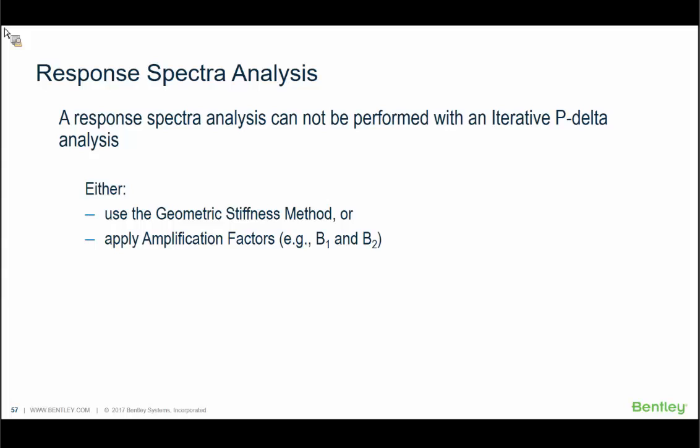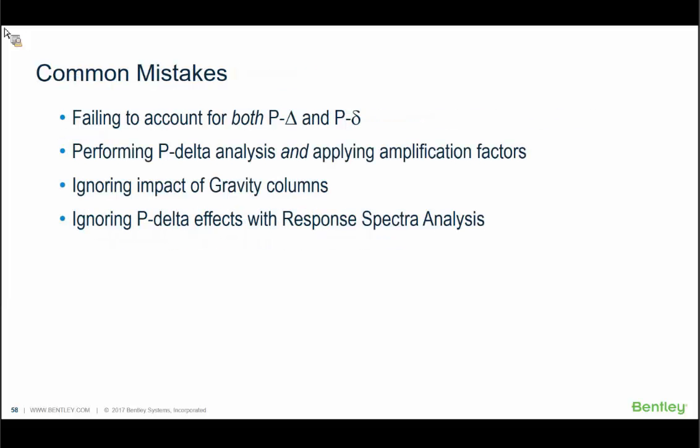So those are two ways that you can account for the P-delta effects when you're performing a response spectra analysis. So here are just a handful of the things to look out for, and again, make sure you understand what your software is doing and what it's not doing to avoid these and other mistakes.